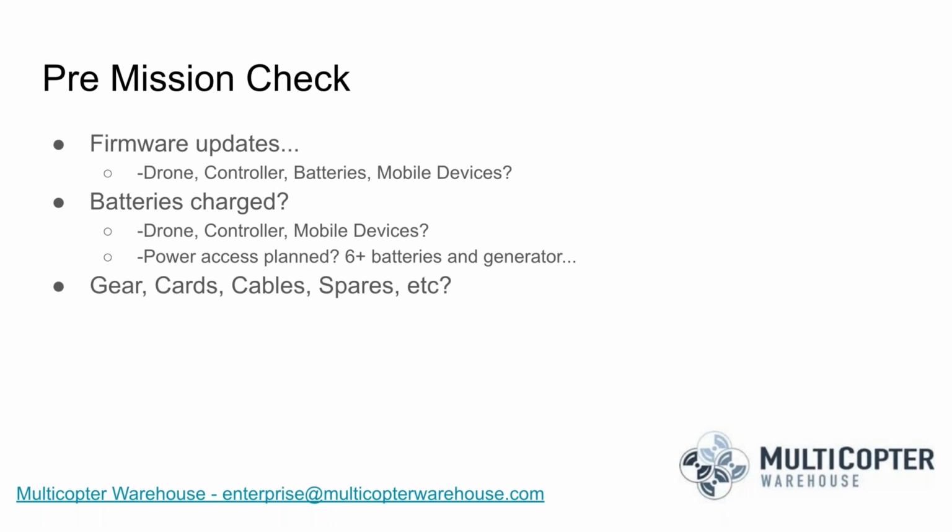What I've found to be one of my biggest limiting factors while doing mapping projects is access to power. If I don't have at least 6 batteries and access to a generator, I can't operate what I'll call continuously. If I have at least 6 batteries, by the time the first one's been drained and cooled a little bit, I can hook it up to a generator, get it recharged, and keep working continuously. But you will be limited ultimately by how much access to power you have, in how much area you'll be able to map.